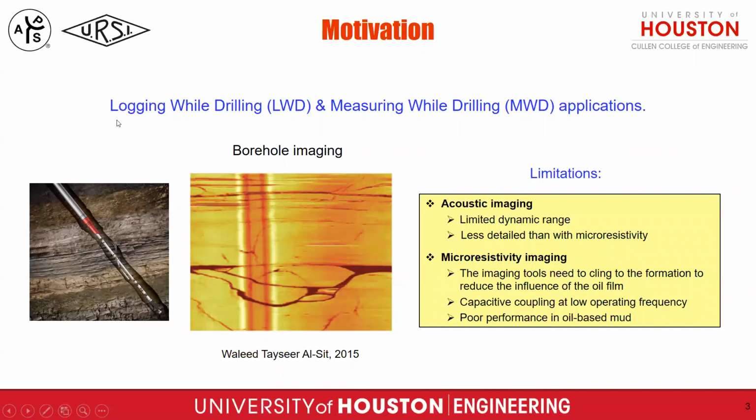Today I'm going to talk about one target application in oil industry, that is borehole imaging. So in the left figure, you can see the logging tool going down in the formation. The sensor on the logging tool will take some measurements. The measurement data will be used to get the borehole imaging. So we can see in this figure, the borehole and some dark curves. The dark curves denote the crack, fracture, or something else.